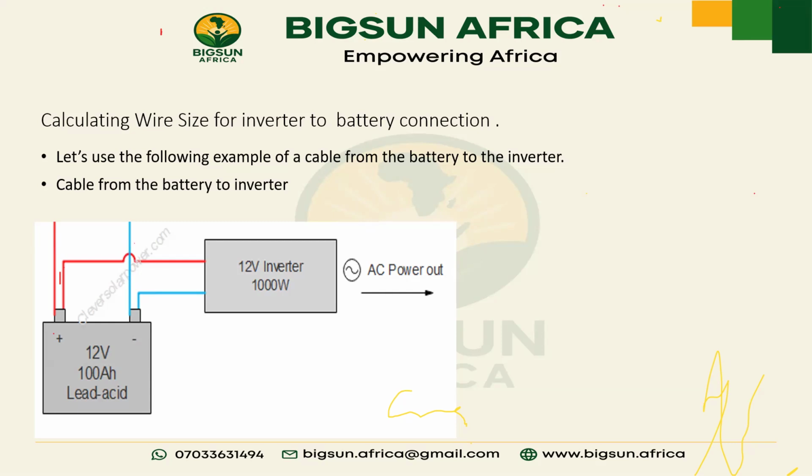How many people agree with him? I agree, if he's connecting in parallel. I agree, sir, because the inverter must see all the 4 batteries as one. The inverter is 12 volts, so the voltage of the battery needs to remain the same. So it has to be connected in parallel, so I keep it constant.